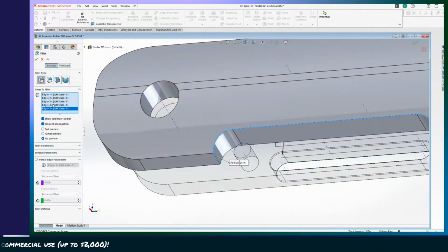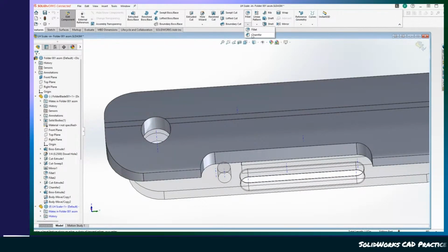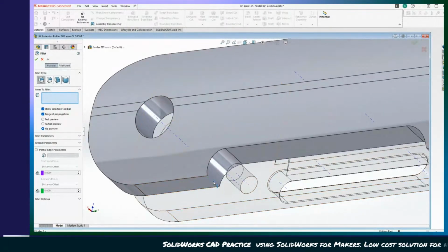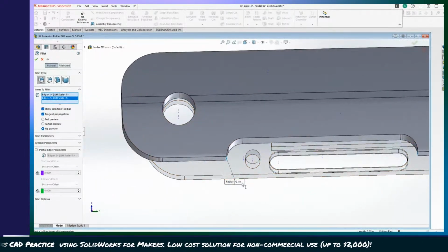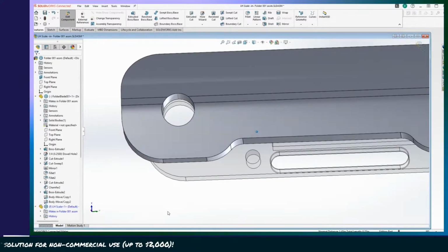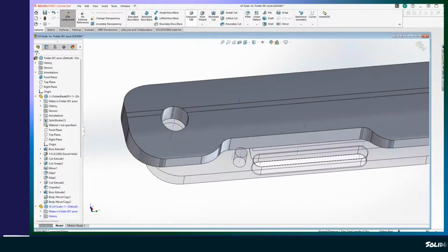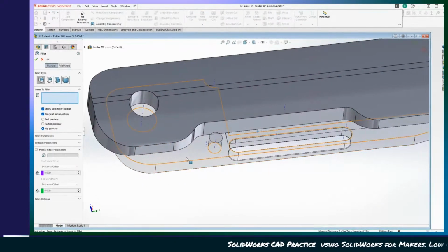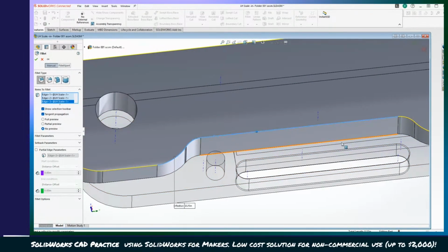Do we need to make that a different style fillet? So let's try just these first. And I'll make them big. Those can be a 1/4 inch. Now let's fillet this surface the whole way around, I guess.